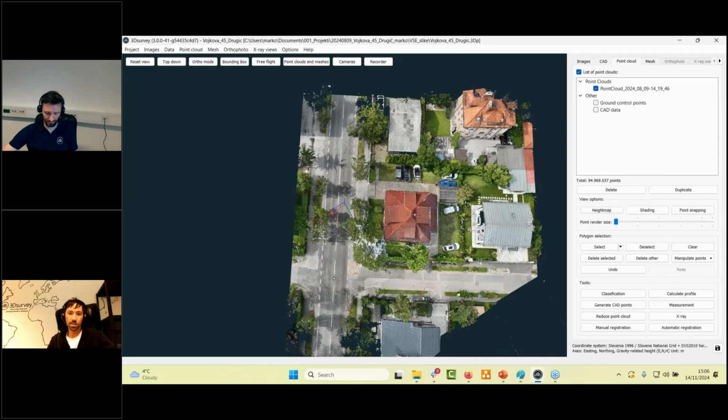So our general advice is, if you have urban areas, you need to calculate a true orthophoto. If you have a construction site without buildings, or big areas in the middle of fields with no buildings, nothing there, just bare terrain with some vegetation, do a traditional orthophoto. The benefits of traditional is you get a bit better texture, so you see a bit more detail in comparison with the true orthophoto, and it's faster to calculate. Okay, thank you, Marco. Then we have Vincent.